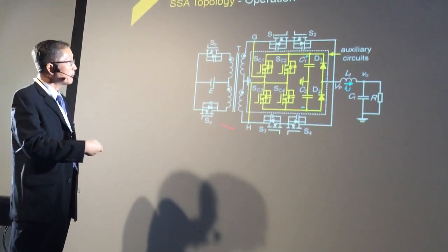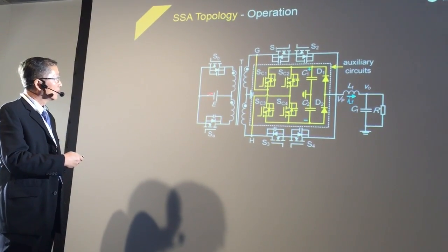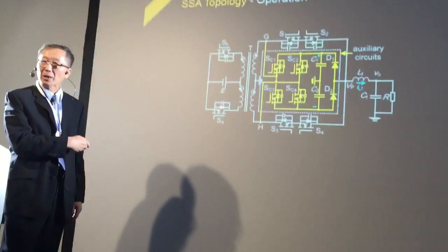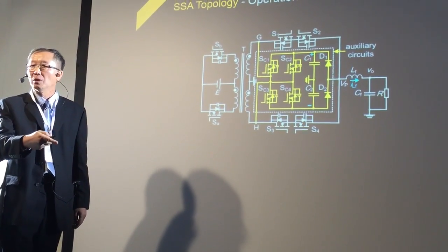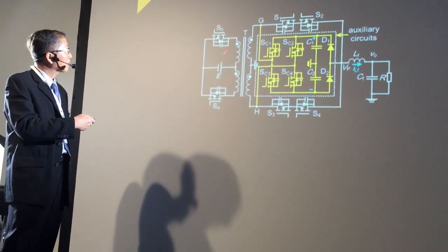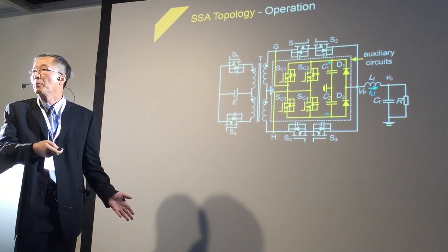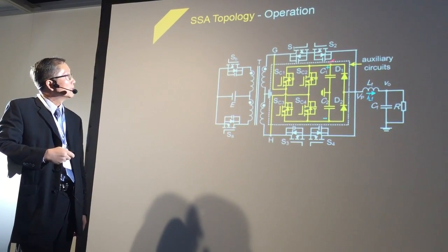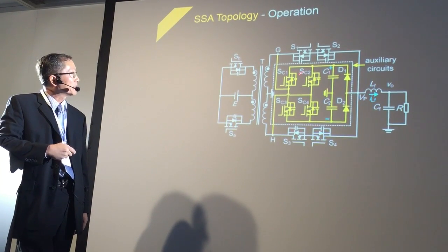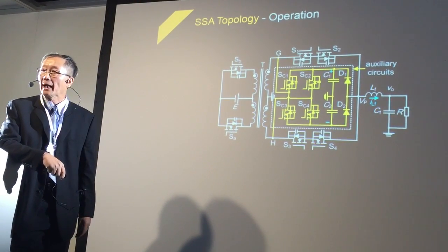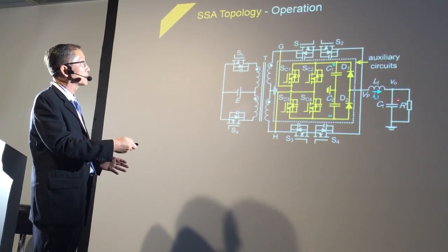Here's the simplified circuit to show you how things work. First, we have an unregulated DC power supply. It can be a battery, or whatever DC voltage that has a large ripple, unregulated. Then we have a primary switch to drive our isolation transformer, because the isolation transformer is so important for safety. Then we have a pair of bidirectional switches. And very important, the heart of this invention is a bidirectional energy tank, to store the energy from either the primary side or the secondary side.